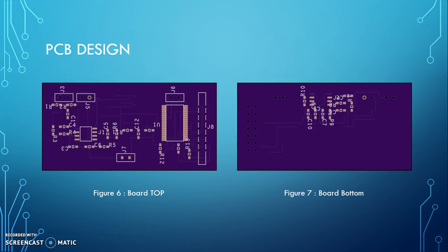Now is the PCB I ordered, which has several mistakes printed on it. There were some places where there are solder masks, but it shouldn't be there. I later had to scratch with knife and tweezer to clear some of my pad stacks. Since the ordered one did not have drills for some pad stacks, I soldered wires on the pad stacks and used breadboard to connect my PCB to Arduino, and of course for programming the microcontroller.